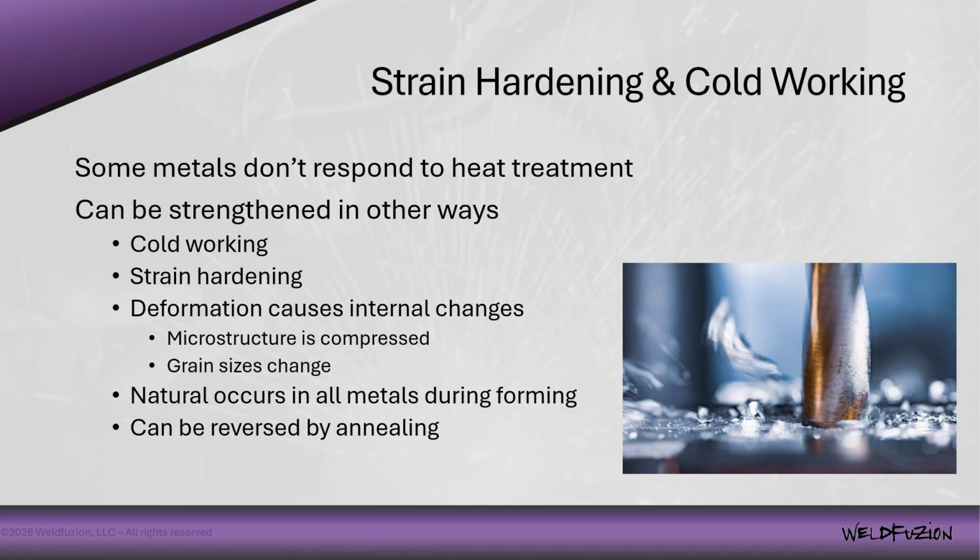So weld metals can be specially formulated with certain elements that encourage the formation of small, fine grains. They call these grain refiners, and that helps the weld metal be stronger and tougher than the weld metal around it in many cases. And cold working can also be done to mechanically alter the grains, whether we're compressing it, straining it, pulling it, bending it, drawing it, any way that we bend this metal, we're seeing work hardening occur, typically during product formation. In the case of certain materials, once they're work hardened, we may want to anneal them to prevent tearing, ripping, or straining.